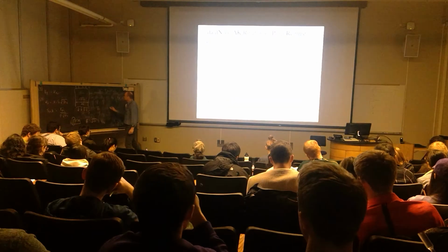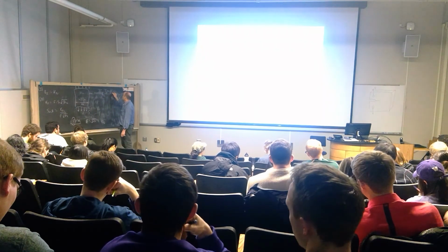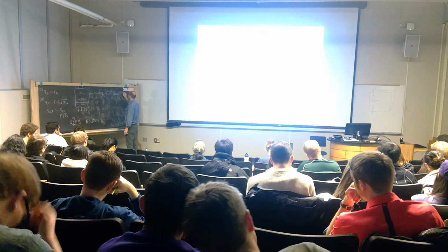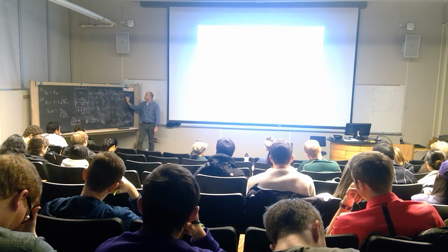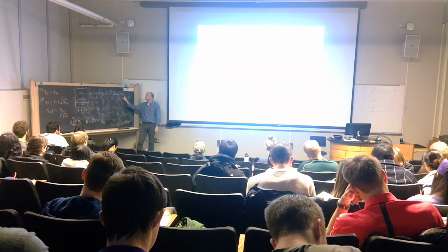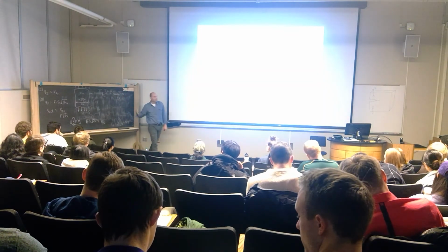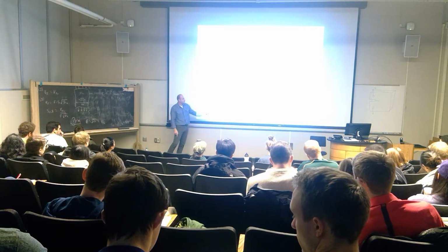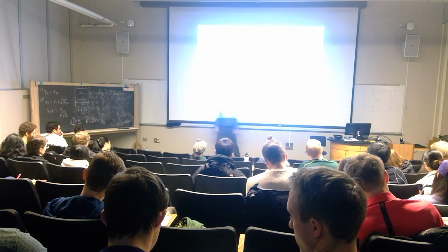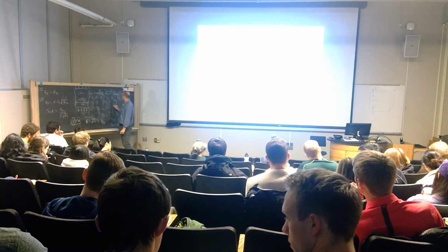So if we say we have a structure in which fracture will take place according to linear elastic fracture mechanics, the fracture will take place when this is true. When we have a fatigue cycle, we want to know what the maximum stress is in that fatigue cycle, and then we know that fracture will take place when that crack reaches a critical length, right? The length that enables fracture, or f for failure, all right? So this is simply saying that the critical flaw length is going to be equal to this.